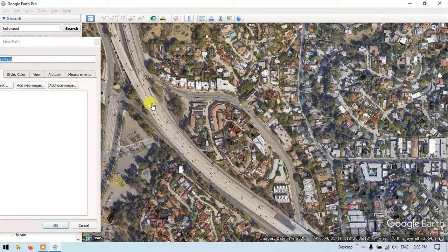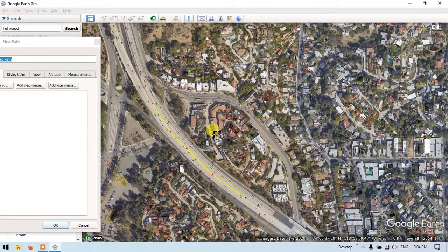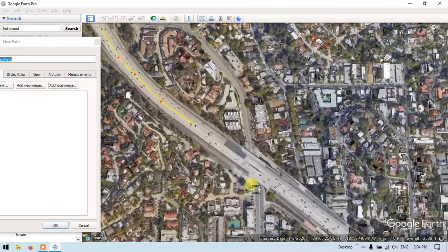Press the button R to stabilize your image. So if it is not appropriate, you can just drag it and make it appropriate, so that you may match the shape of this road. If you put more points, the shape will be much more accurate.